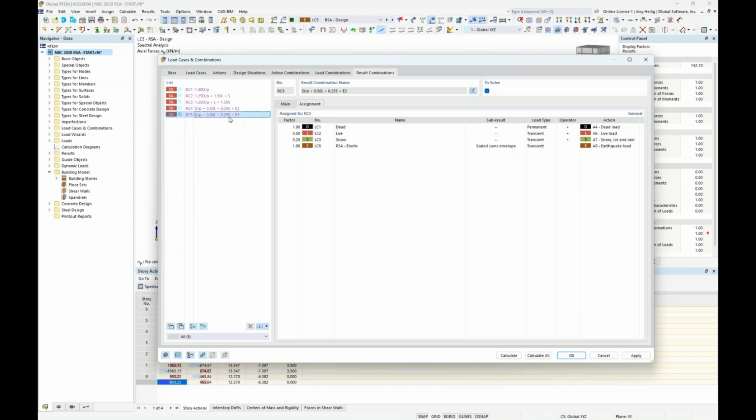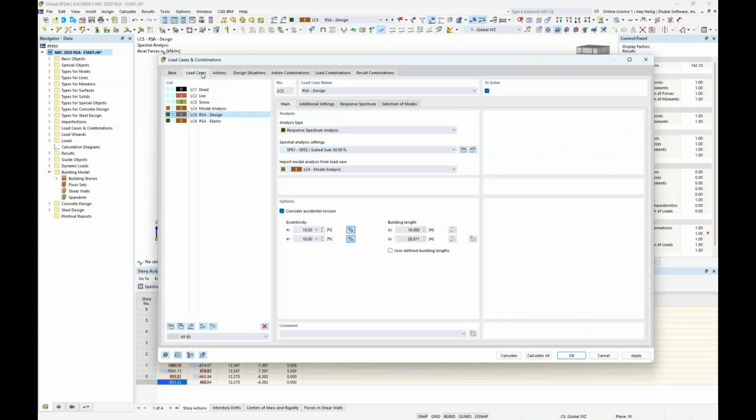We also see a second result combination with our elastic response spectrum analysis. And for this, we actually refer back to the NBC Commentary 2015, and in particular, Appendix J, Note 111. And the commentary tells us that earthquake loads are considered rare. So there are no general requirements for SLS design when considering earthquake. Rather, we take a look at the specific elastic response spectrum analysis to make sure that our drifts, in particular under only earthquake loads, are limited according to what the code has said. Therefore, I really don't need to include this in my load combinations as well.